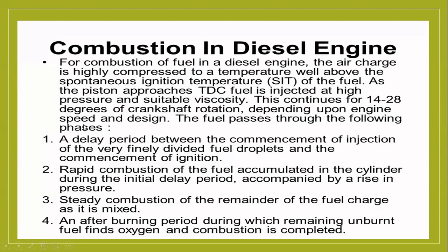Depending upon the engine speed and design, the fuel passes through the following phases. A delay period between the commencement of injection, with the fuel very finely divided into droplets, and the commencement of ignition. I told you, don't write too many things. You will write: fuel will divide into droplets, atomization, then only the ignition will take place.